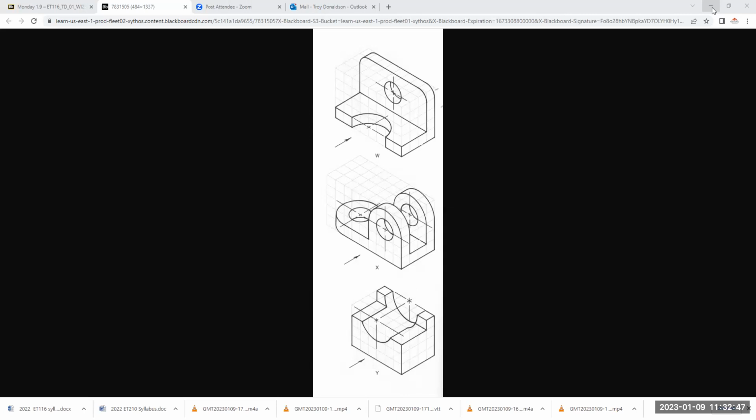We want it 1/8 inch there, not necessarily what goes into the really big drawing, or you wouldn't be able to see it. So the way to do that is to set the height in dimensioning and to use annotative dimensioning. Annotative means it's going to look at the scale and adjust for you. Not going to be a problem.